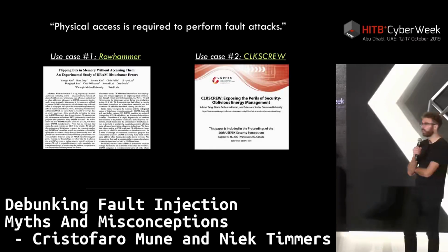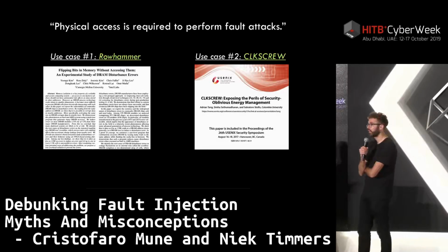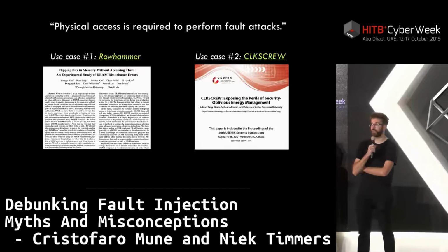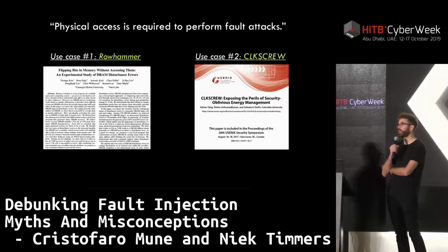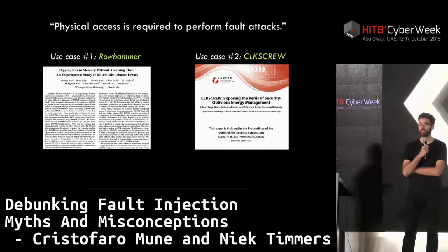Now, another variant is actually Corkscrew, which we briefly referred to. The idea here is that by software, you can actually change the voltage and the frequency supplied to the chip. So by making configuration changes to these two settings, it allows you to run a chip outside of its expected conditions. Exactly what you would be doing with voltage glitching.